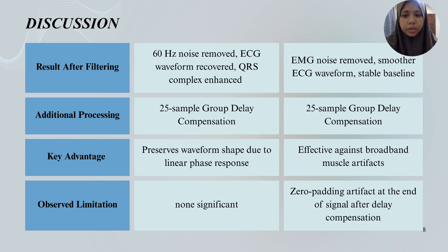However, a small artifact can be observed near the end of the filtered signal, where the waveform suddenly drops to zero. So this occurs due to the group delay compensation process, which introduces zero padding at the end of the signal. So the FIR low pass filter successfully improved ECG signal quality by reducing noise while maintaining the essential characteristics of the cardiac waveform. That's all from me.